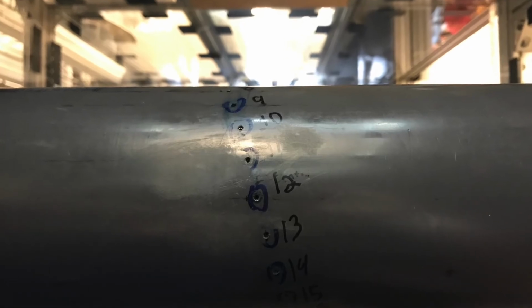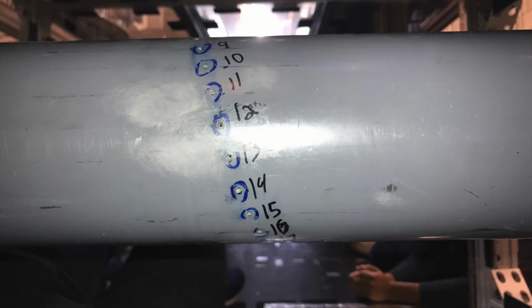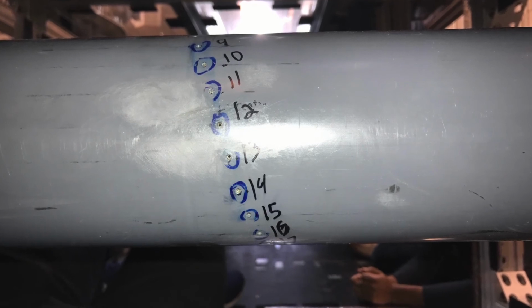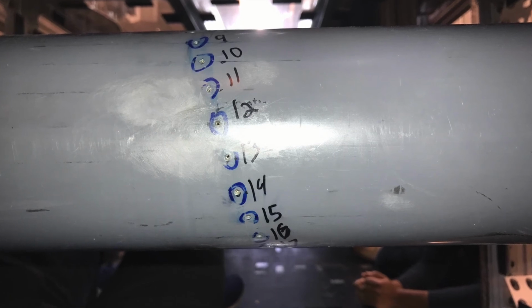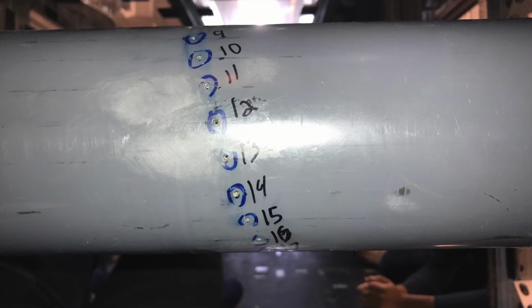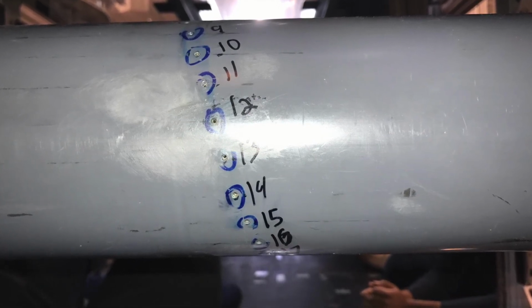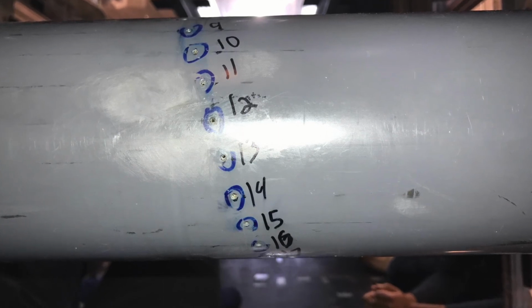Lastly, a total of 24 evenly spaced static ports were used to measure the pressure distribution around the cylinder, and pressure values were uploaded to MATLAB and used to calculate velocity and pressure. Furthermore, LabView was used to determine the flow velocity in the test section through the pitot-static reading. Any possible sources of error were noted and photographed to be reviewed in the case of unusual data.